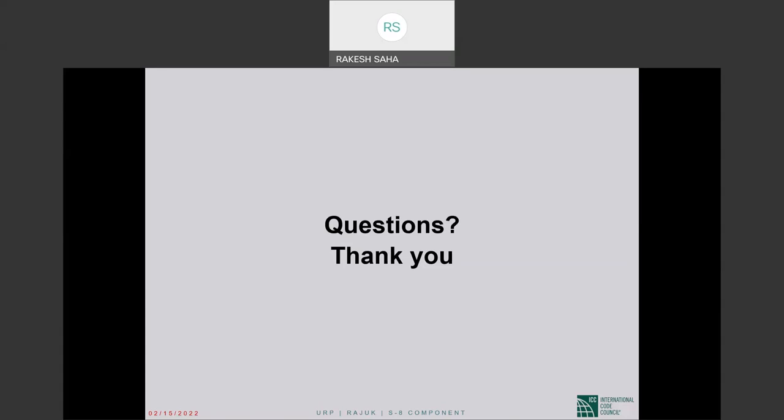So it is not that you need to check drift, you figure out whether to do static analysis or modal response spectrum. It is the other way around. You make a decision that your design shall be based on modal response spectrum analysis, probably because you have a tall structure and an irregular structure. And then you will have to do drift check as always, and you will also have to account for torsional irregularities if there are any.